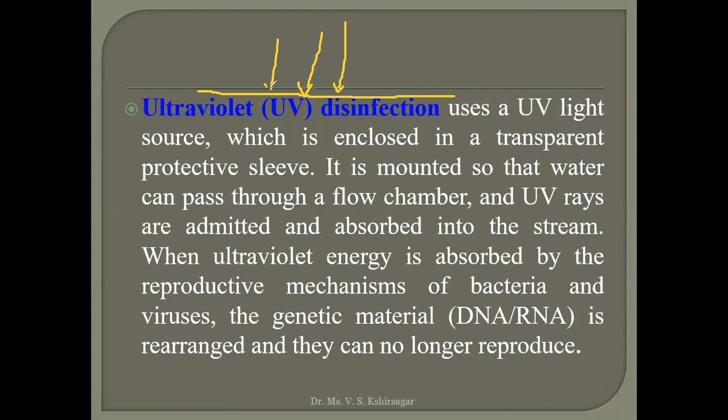When ultraviolet radiations are coming and passing through this thin layer of water, at that time, it is penetrating. We should take care that the thickness of water must be very low to allow the ultraviolet radiations to penetrate up to the bottom. The penetration of ultraviolet rays must be done up to the bottom. Then and then only it will kill the entire bacteria.